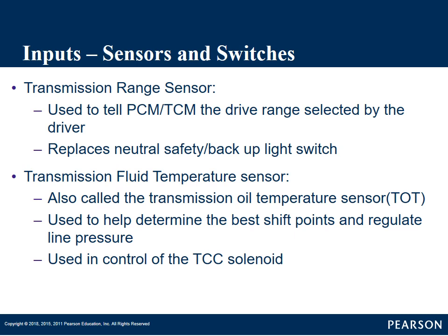When the vehicle is cooler, line pressure is going to be higher because seals, when they're cold, don't seal as well. So they're going to increase the line pressures, make sure those clutch packs engage properly.